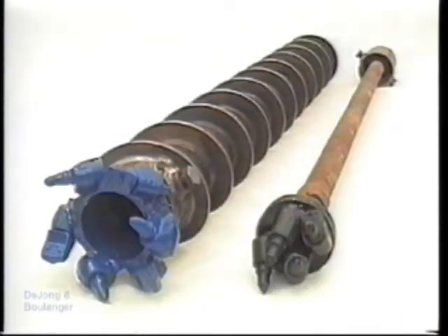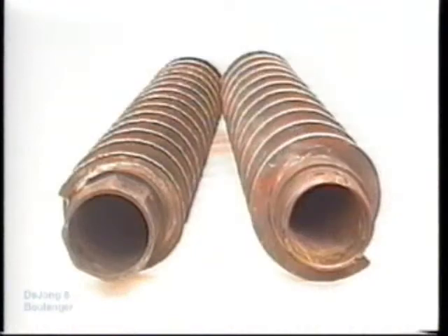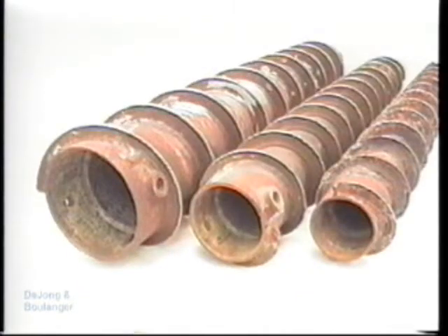The basic hollow stem setup is shown here. The inner bit is connected to drill rods that run through the hollow stem, and the other bit is bolted to the bottom of the lead auger. While drilling, the inner and outer bits rotate together, cutting and loosening the soil at the bottom of the hole. The soil cuttings are carried upwards by the auger flights to the top of the hole. Hollow stem augers use 2 types of connections. The auger on the right uses a 2-key connection, while the auger on the left uses an octagonal connection. Hollow stem continuous flight augers typically come in 5-foot sections, with inner diameters from 2¼ inches to 12¼ inches.